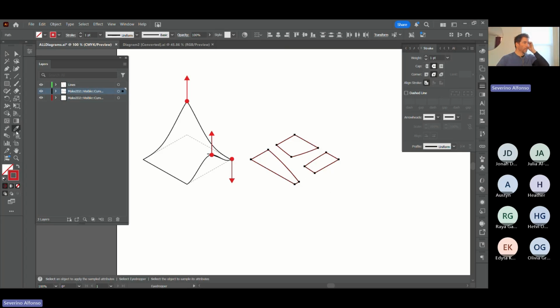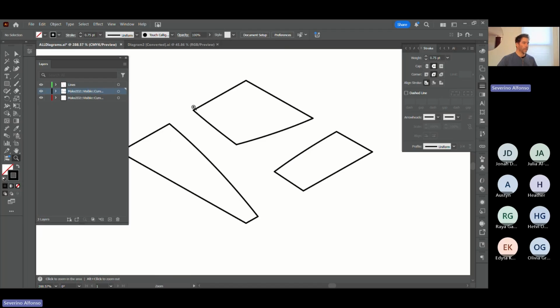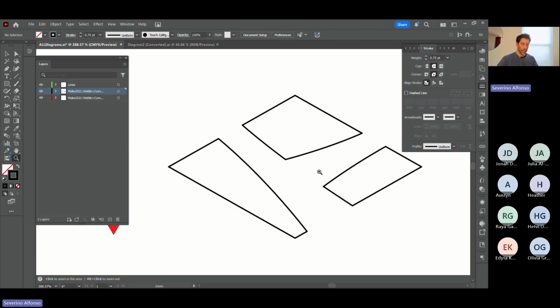And now what I'm going to do is select the things. This is the tool. I stands for eyedropper, which means that whatever you selected, you can match the properties of something else that you select now. Select that. And all of these things that I have selected will match the line weights and everything from this setting on. So now I could reference the origin. I could bring a square here and do the same as I did before, but I can also just draw this because it's very simple. I can snap and snap. Let's see that work. No.